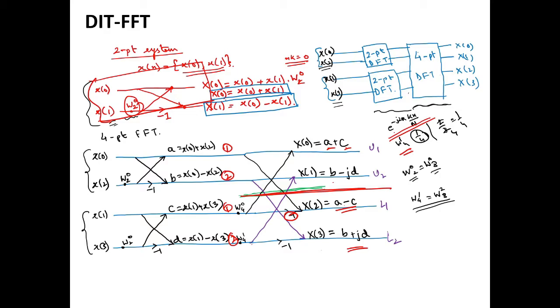W14 means that kn by capital N is 1 by 4. If you get a value, say 4, it means we are performing 4-point DFT. When we have an 8-point DFT and you get a value 2 by 8, it is again W1 by 4, because top by bottom it is again 1 by 4. So W14 is equal to W28. That you need to keep in mind.